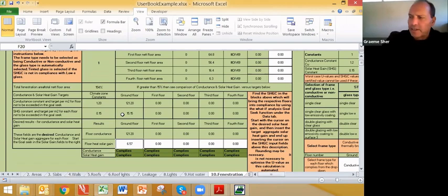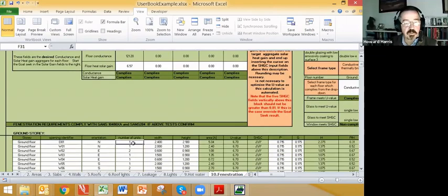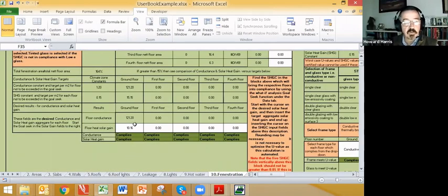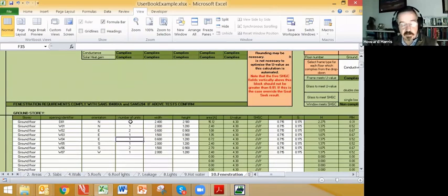Maybe we should increase the fenestration so we're not compliant, and then we can do the goal seek. All right, let's put 3 windows in the model, a theoretical 3 windows, and here you can see we're not yet out of compliance, so we need to probably push that to quite a lot more, Graham. So we'll put 6 windows in there,